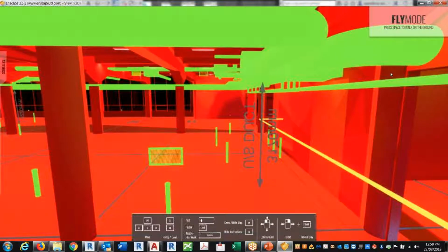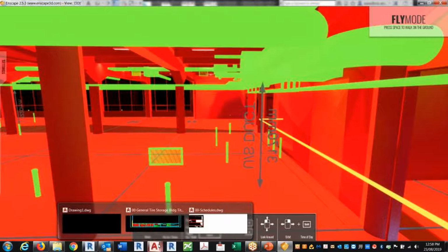All right, so that's pretty much it. To conclude, if you guys have any questions, feel free to message me or just ask me, so I can help you out. Shared coordinates is not the easiest thing to learn, but once you learn the basic concept of how to acquire coordinates, how to position it properly, and then how to reset it, you basically master the whole shared coordinates. One thing I tell people: don't trust that internal button, because that thing can just drive you nuts. I don't know what they're trying to do. So don't bother with what Autodesk tells you, because I don't think they even have this figured out.